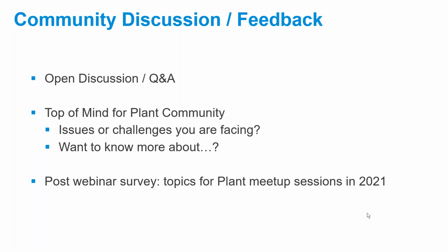Yeah. So there's some simulated annealing, which is a programming term for the technique they're using for optimizing the layout on the isometric sheet. And there are some settings in the ISO config for that aren't available through the user interface when you're doing the setup for isometric styles. I've played with them quite a bit. A couple of them actually make notable differences. Some of them don't really seem to do much at all. So you kind of have to experiment, on a non-production project of course, and I'm sure a lot of you have done that too.